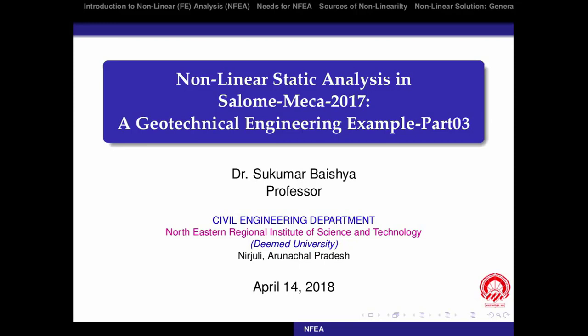In this part we'll see how the slope geometry is created and then how meshing is done, and then we'll use the Aster study module, which is newly available in Salome-Meca 2017, to create the COM file, the command script which is needed by the solver Code-Aster, and then finally we'll analyze the slope. So here we go.